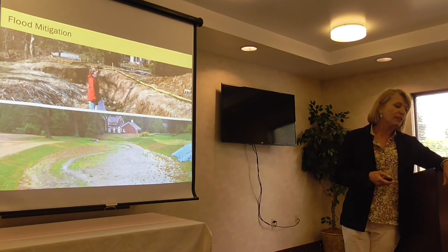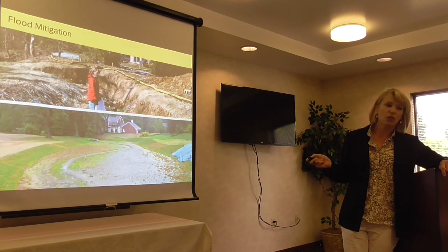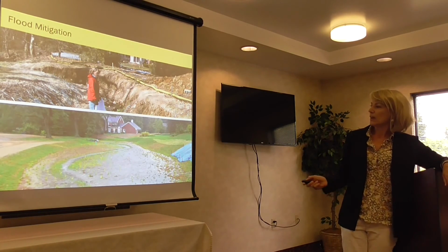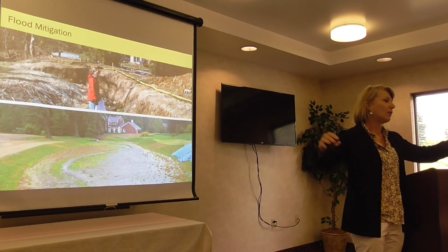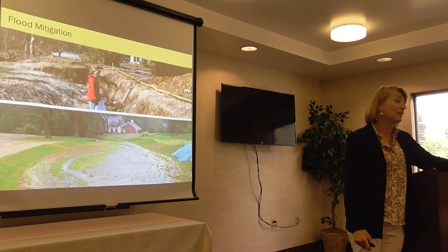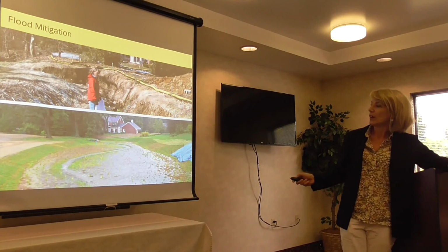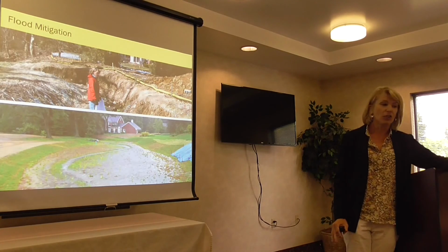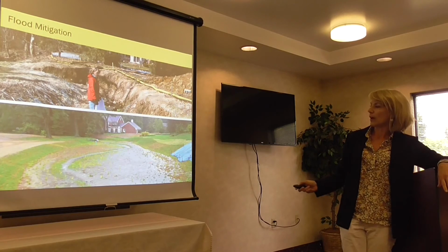It's on a residence, so it's a little bit smaller scale at this point, but the whole point is looking at ways that we can restore the floodplain and mitigate flooding, provide that storage area by allowing those floodwaters to spread out, restoring our floodplain so that it floods is what it comes down to, and using those areas to provide the volume and also to reduce the energy to dissipate those flows across the whole area.